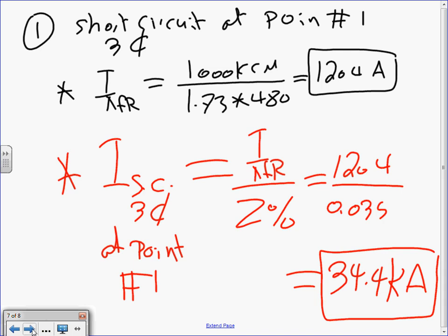Even if you turn everything on, you have everything running, it's still overloaded. You want to load it. You never load it. You know why? Because remember when we sized for motors, what did we do for the full load current of a motor? Multiply it by what? But these are not real. They're for safety factors. Imagine all these safety factors, keep adding them up at the service. You end up with at least 25% oversized, 25 to 50% oversized system is typical for future safety and all this stuff.